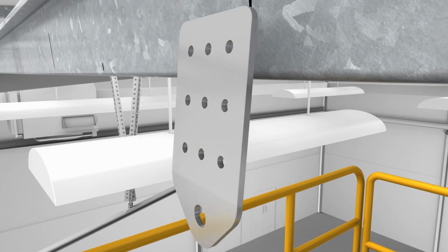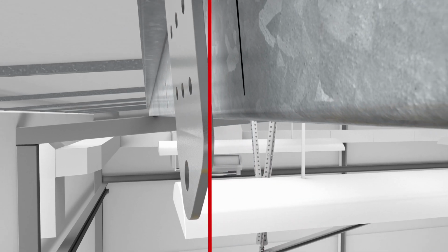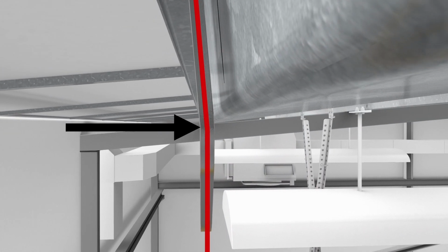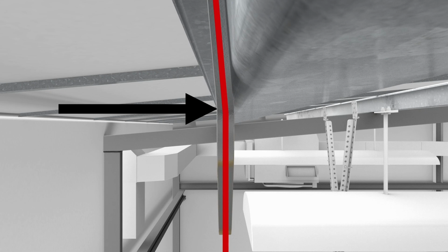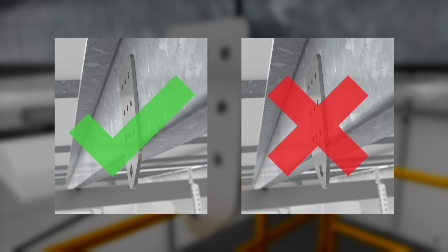To aid horizontal alignment of the Kee Track system, the perpendicular purlin brackets incorporate a bend above the hanger link arm fixing hole. The bend must face towards the lowest purlin relative to the roof slope onto which the bracket is being attached.